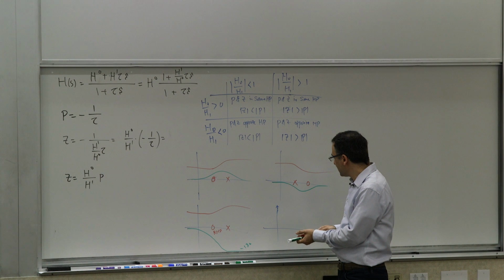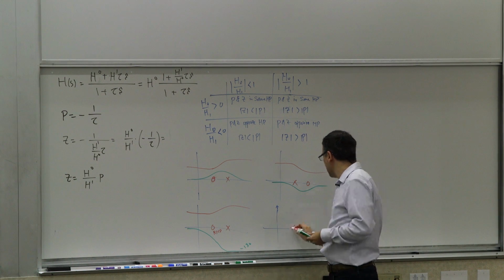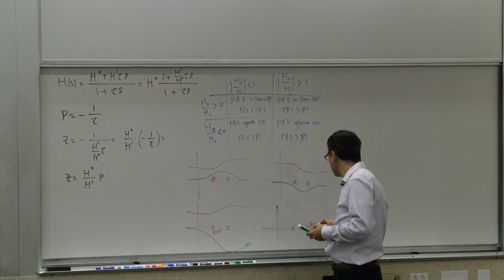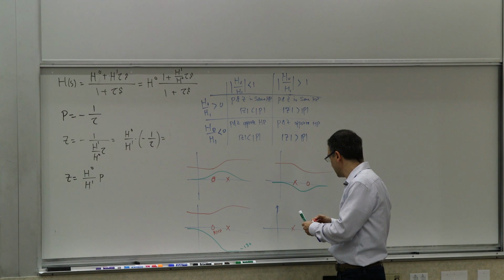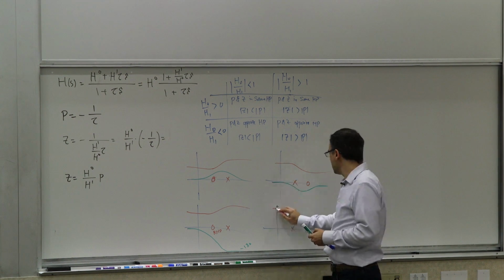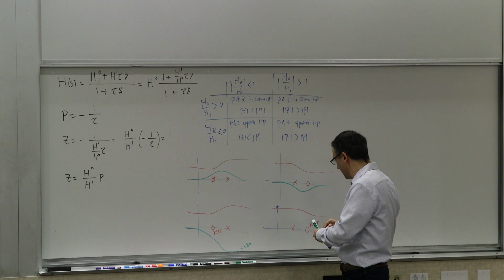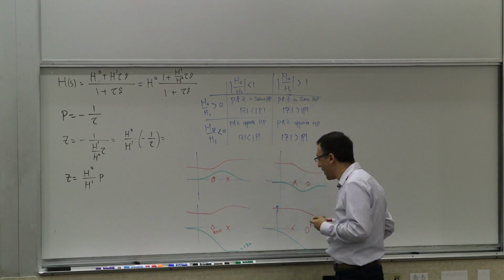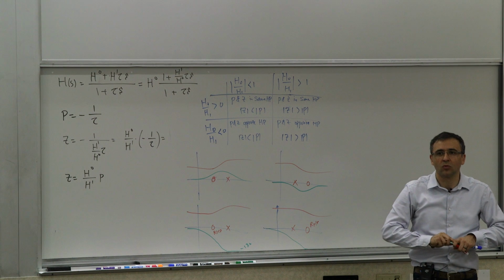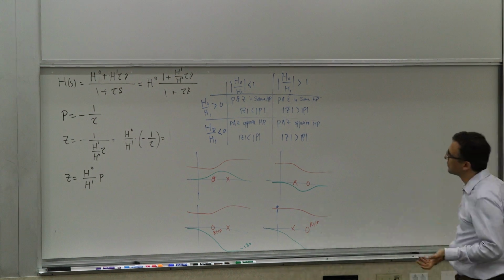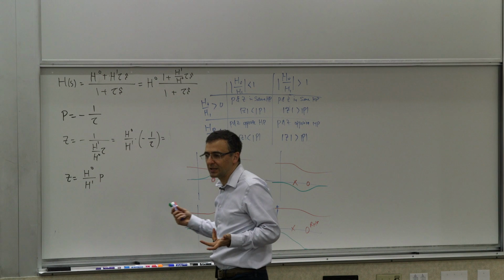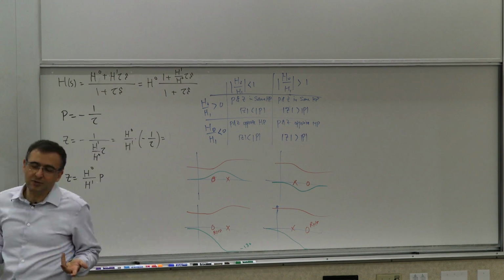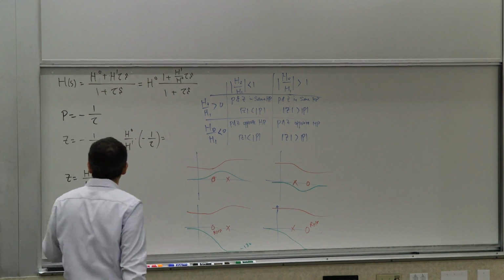Now, if you have the opposite scenario, again, you have a pole and a right half plane zero. Again, the amplitude response would look like that, but the phase response will start dropping this way. So you have four different frequency responses based on this. You can easily tell.